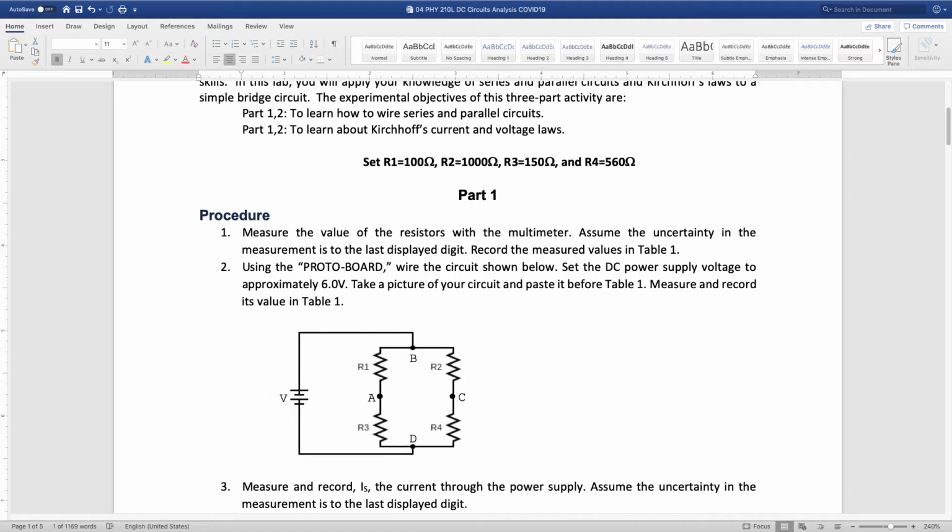One student didn't get the 560 ohm, but he said he had a 220 ohm and a 330 ohm resistor. He put them in series. I thought that was a great idea, and so those two replaced the 560. And if you wanted to buy a resistor, they are very cheap. I think Fry's might still be selling those.